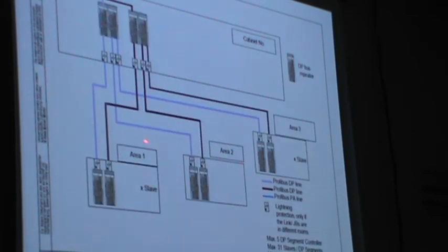And you can increase the number of repeaters like this. This is the DCS and you have only 2. From there you can put the loop. You can take it to the field, many different areas, and here also you can still go for extension and communicate with the field instruments.